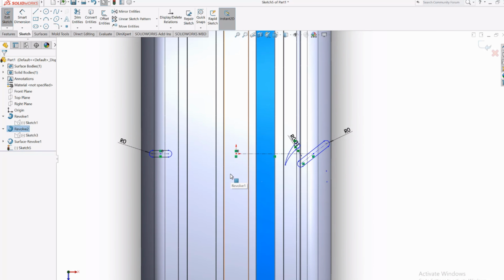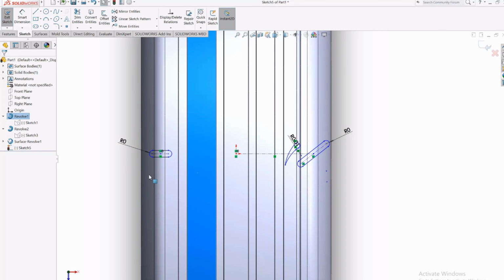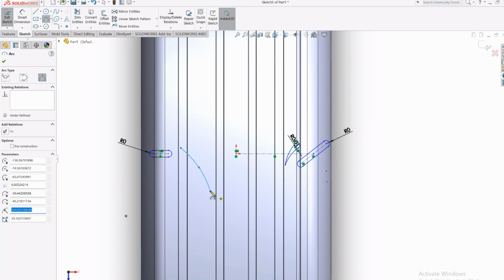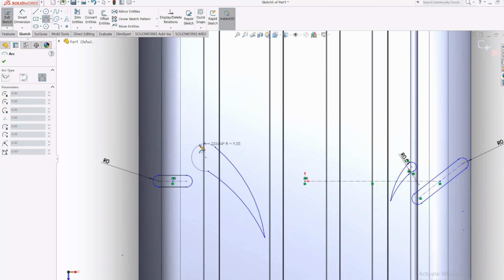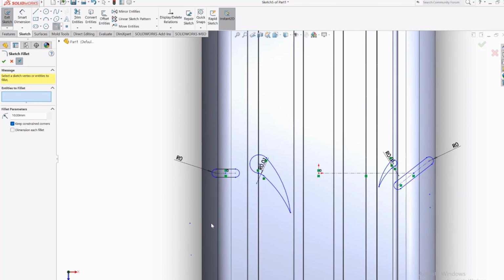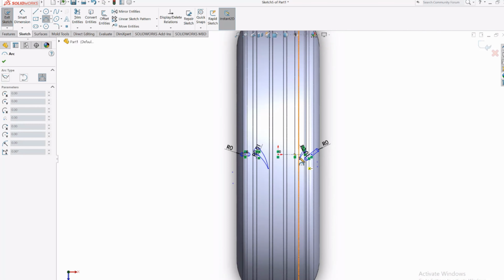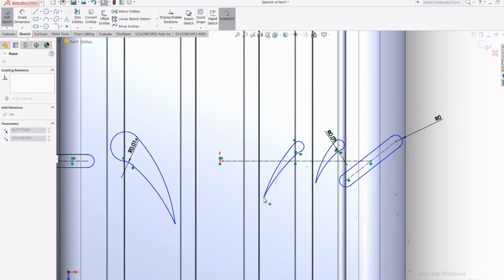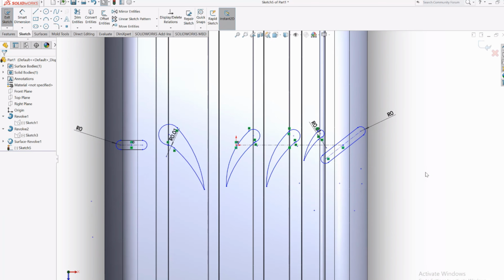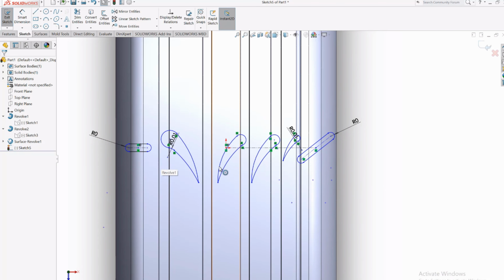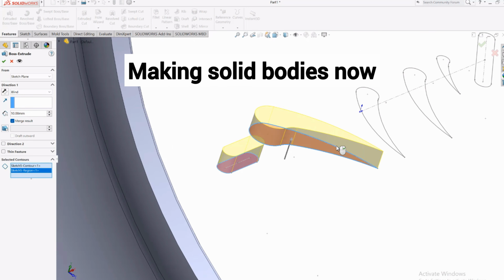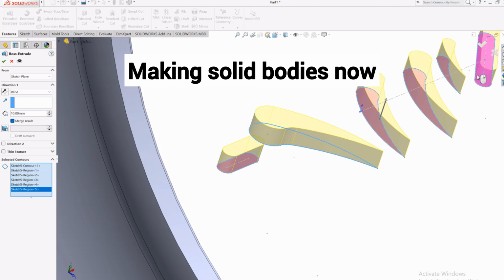Make sure it goes into the vicinity of the groove cutout area so that water can be directed into the groove channel. Similarly, make one opposite and longer design on the left-hand side in same way. Just like this, make 2 more on the other 2 ribs as well. Now our sketch is ready. In this sketch we have made cutouts for shoulder and sipes for tread block detailing and groove.